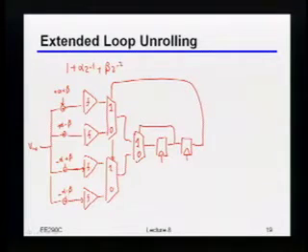Okay, so now obviously you can keep on doing this, but clearly your complexity is going up exponentially with the number of bits that you're trying to unroll. As somebody asked, I think last time, at some point this starts looking a lot like an ADC. Because you can imagine if they have a lot of ISI, then the reference levels start looking fairly uniformly distributed. At that point, you might almost as well just build an ADC and then figure out what the right answers are afterwards. Okay? So indeed, this works.